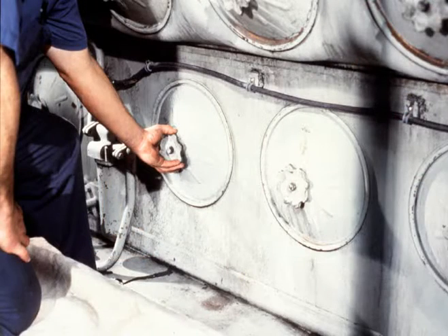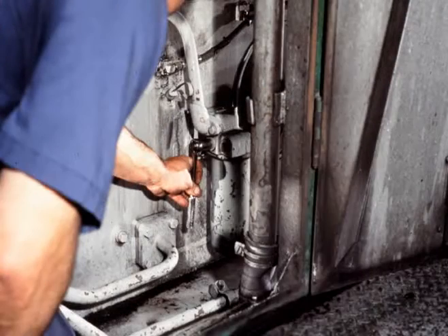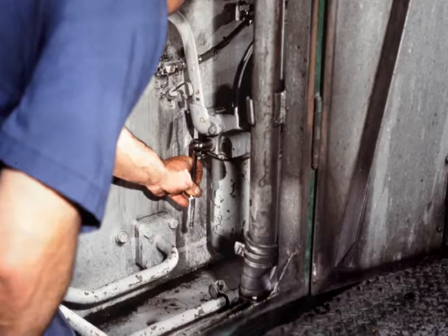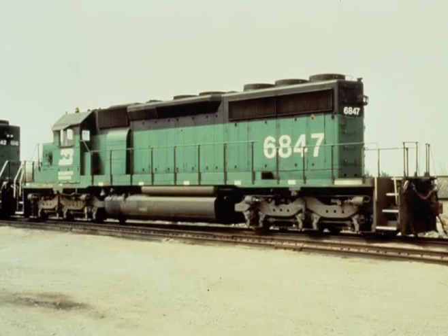Remove the oil pan cover nearest the soak-back pump. If you hear oil flowing back into the oil pan at this location, the problem is probably a stuck relief valve in the soak-back filter head. Remove it and clean any sludge or foreign objects from the seat. If the proper maintenance is performed and the systems are qualified, the EMD lube oil system should perform reliably until the next maintenance period.